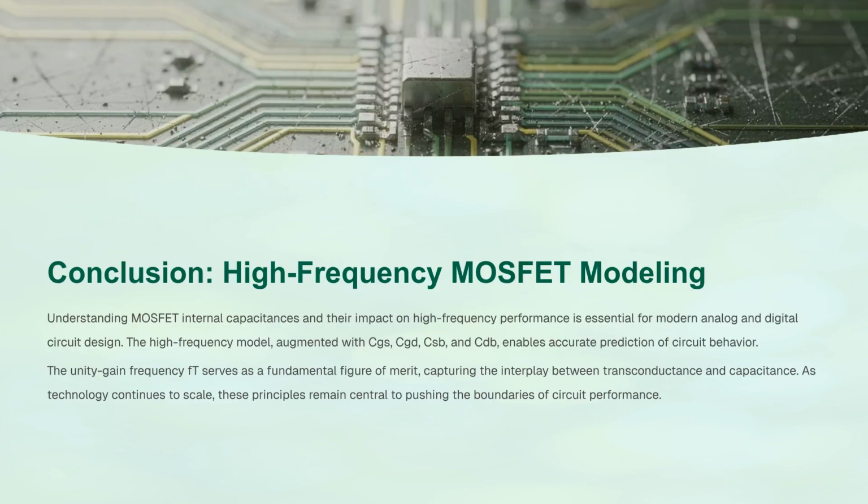Understanding MOSFET internal capacitances and their impact is essential for modern circuit design. The high-frequency model enables accurate behavior prediction, and fT serves as a fundamental figure of merit for performance as technology continues to scale.